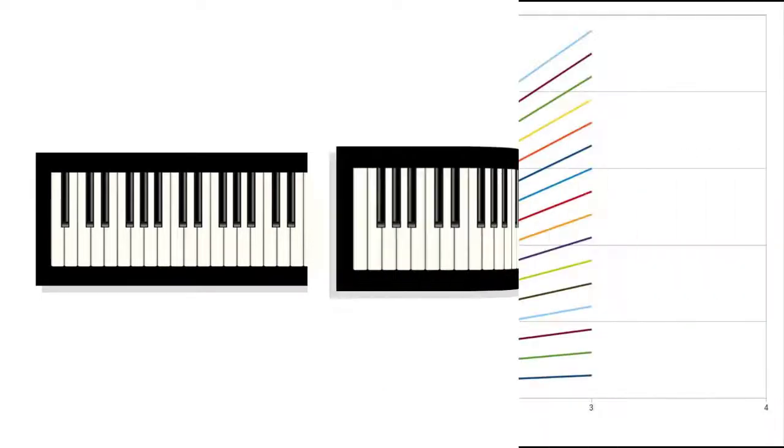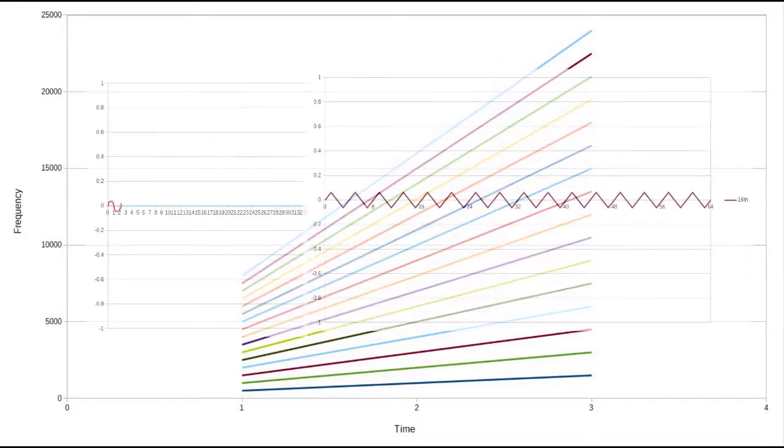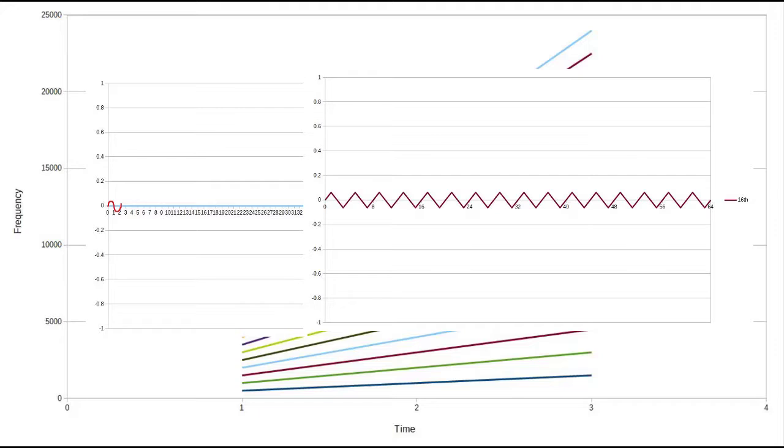Which brings us to table size. We've already found that the theoretical maximum harmonic number is half the table size, i.e. for a 64 sample table the maximum harmonic number is 32. However, we have also noted that the very highest harmonics are somewhat suspect.